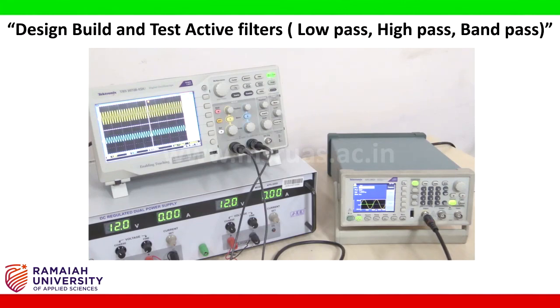After the critical frequency it starts to decrease the output. So from this experiment, or from this design, we conclude that the band pass filter we designed for 1 kilohertz gives a critical frequency of 800 Hertz. So hence we complete the experiment of band pass filter.